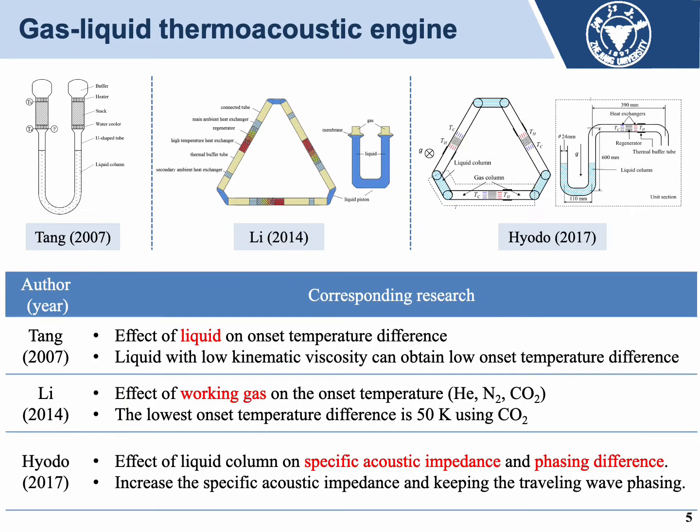One of the effective methods is the introduction of a liquid column into a gas-only thermoacoustic engine, and a series of numerical and experimental studies on gas-liquid thermoacoustic engines have been conducted. Various effects, such as liquid and working gas, on onset temperature difference are analyzed.